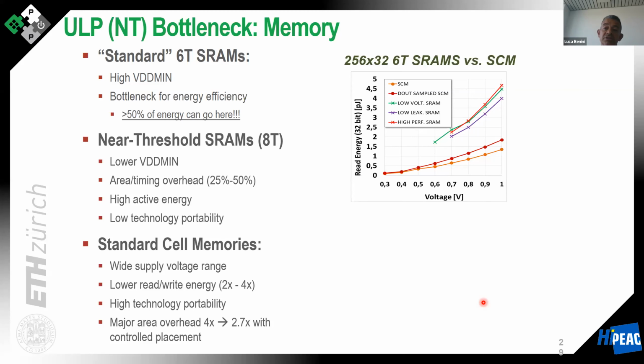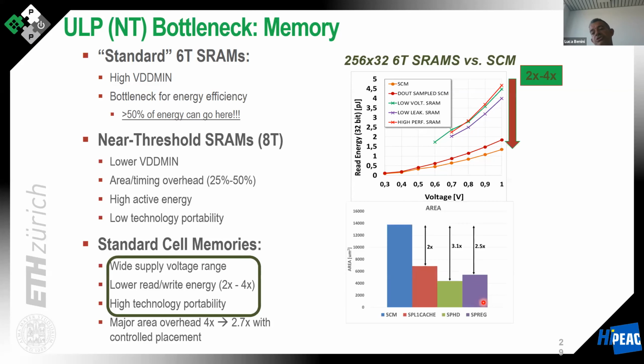What about density? Well, latches have a much worse density than SRAM. So you have a problem. You have much better efficiency in accessing the memory with instructions with latches, but your SRAM density is compromised, and you have to pay a lot of area for this latch-based memory. So how can you solve the problem?